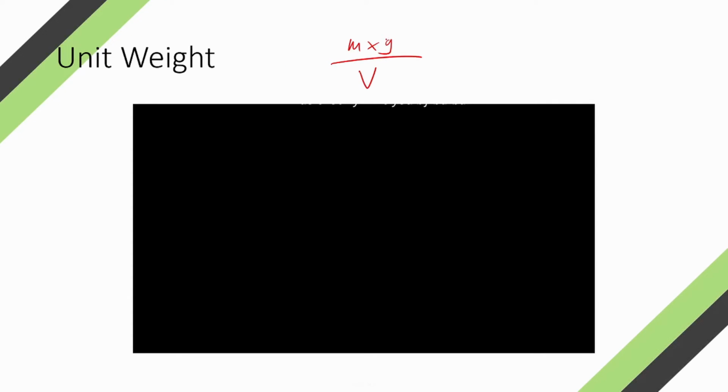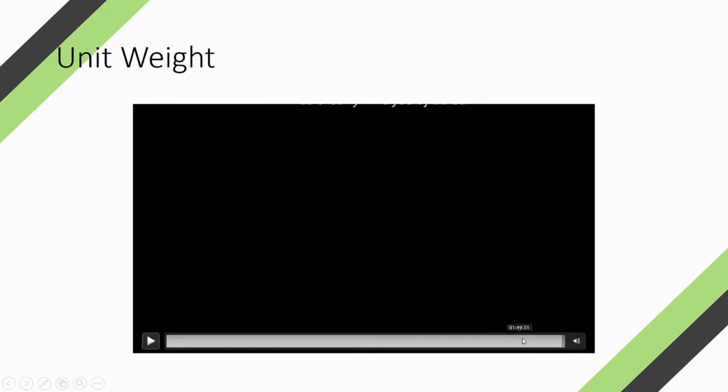If you only use the mass, what you get is the density of your aggregate. So, it's easy. And then, the test says to repeat 4 times and average the unit weights you get. So, that is the test for the unit weight of aggregates.